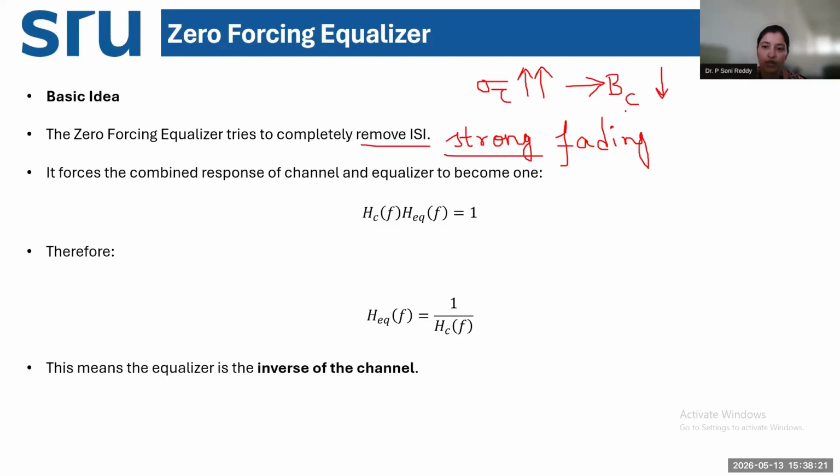When this range of frequencies reduces and becomes less than the signal bandwidth that we are transmitting, that is, when the coherence bandwidth becomes much smaller compared to your signal bandwidth, the channel variation increases with respect to frequency, and you experience what is called frequency selective fading. Now, when does this deep fading happen? This deep or strong fading happens when we have destructive interference experienced at the receiver side.